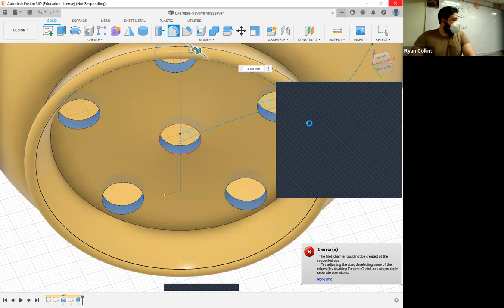I think I overpowered the computer. When you're doing fillets and such, unless you have a fairly powerful computer, I recommend making the adjustments numerically. So instead of using the slider, enter like 1 or 2 and so on.